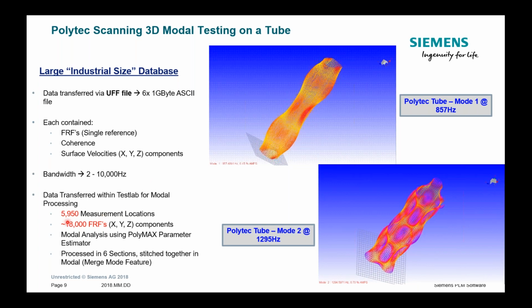That ended up with close to 6,000 measurement locations. And since we were measuring in 3D, that gave us X, Y, and Z measurement points with a 3D scanner, which gave us approximately 18,000 frequency response functions. We were able to use that and do a complete analysis, and these are some of the results. We had mode 1 at 857 hertz and mode 2 at 1,295 hertz.